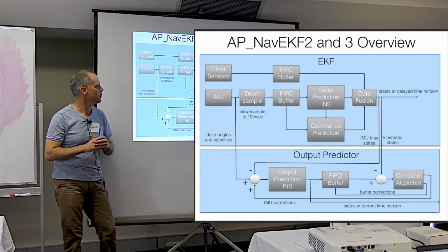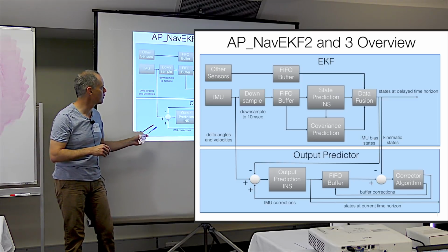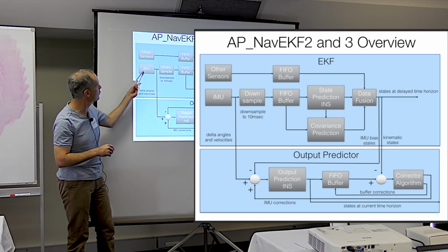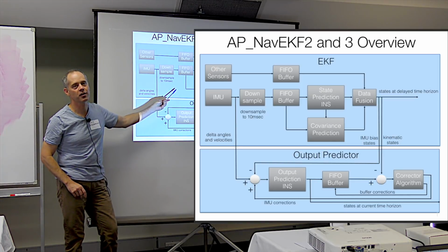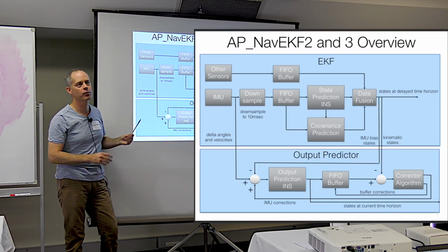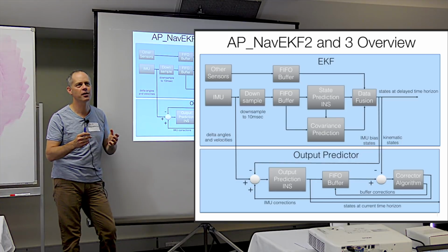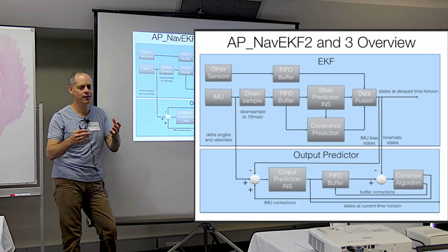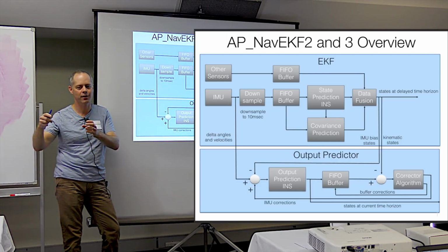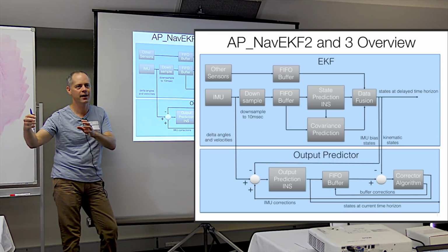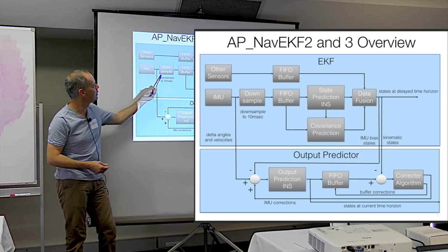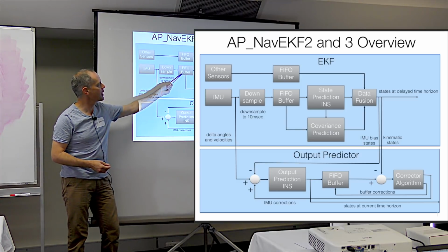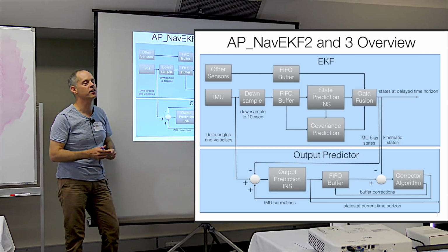The other point, which isn't so relevant here, but also reinforces the importance of the IMU, is the EKF is running about a quarter of a second behind real time. So when you have a look at the EKF data in the logs and you're going, oh, hang on a bit, the roll angle on the EKF, it's delayed relative to the DCM roll angle, or it's delayed relative to something else in my data. The answer is yes, because it's running data that's coming out of a buffer. It stores about a quarter of a second of data.